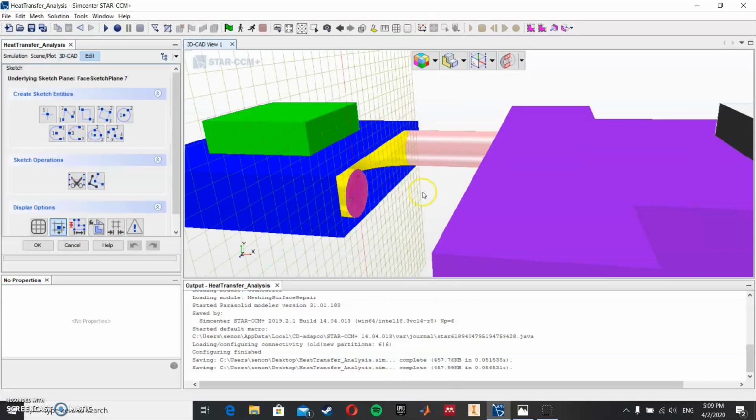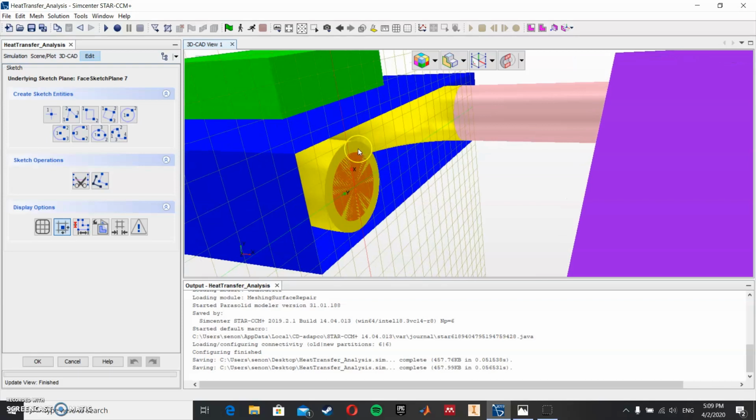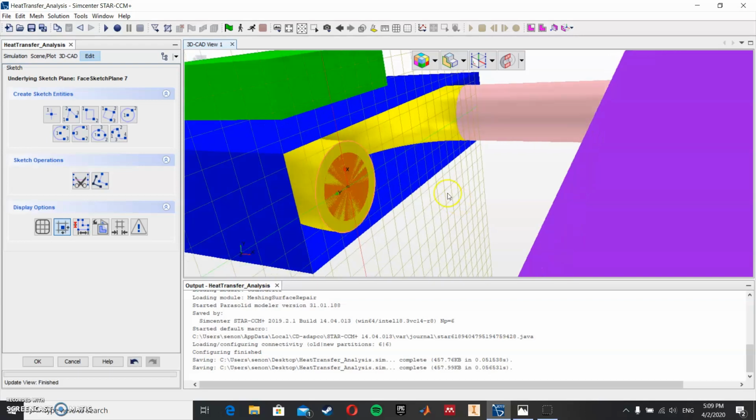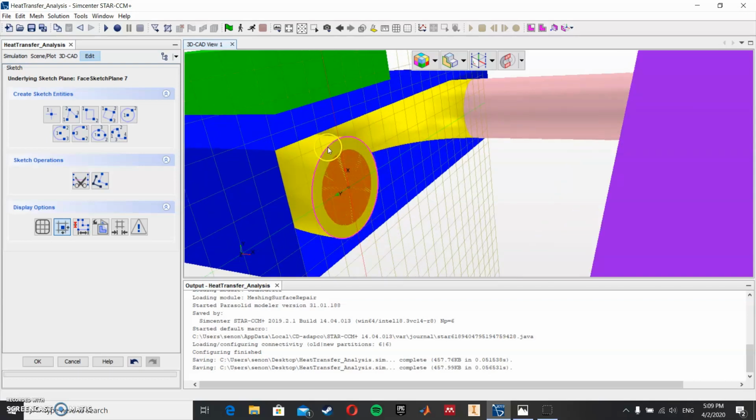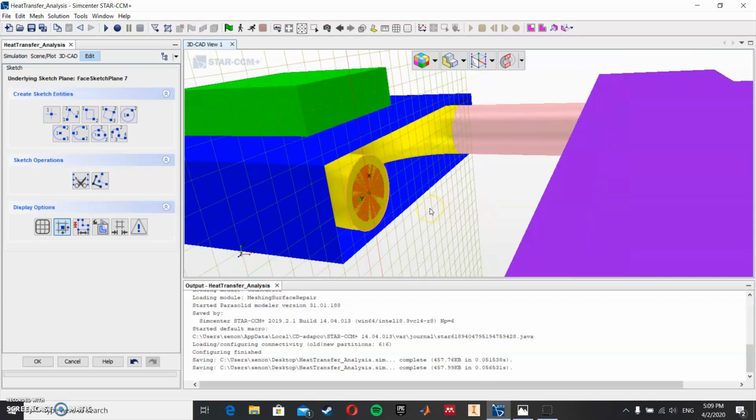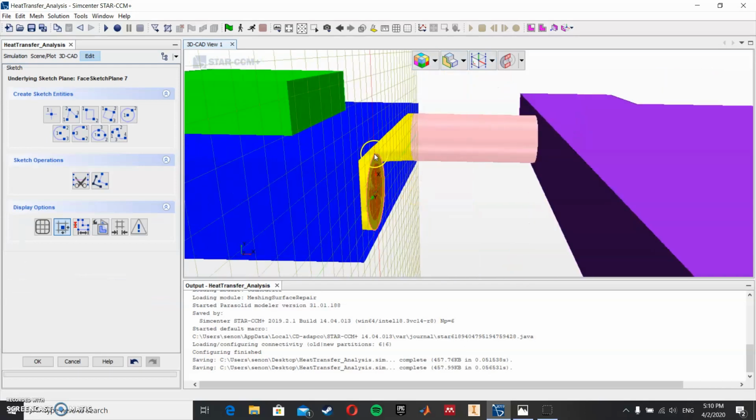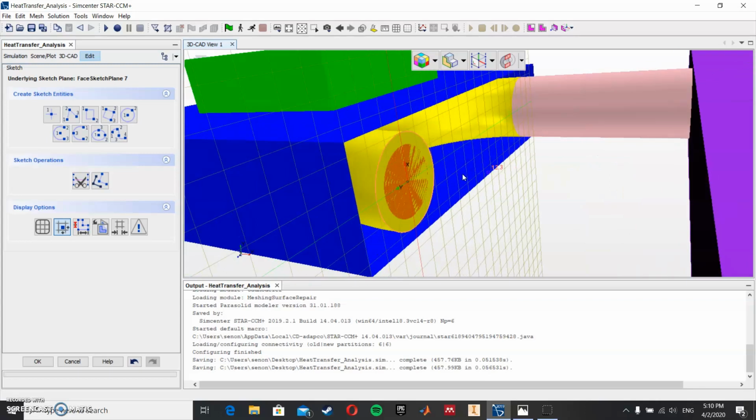Let's create a sketch at face center. What you can also do is project to sketch, okay? So now we see the outline for this pipe, this sketch. But the problem is that since this sketch is dependent upon this body, sometimes when you want to make changes, it becomes difficult since this sketch is affected as well. So the whole thing changes, the whole body you create from this sketch changes as well. So be careful with that.